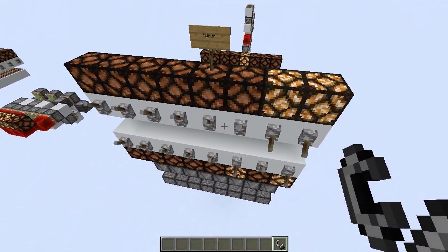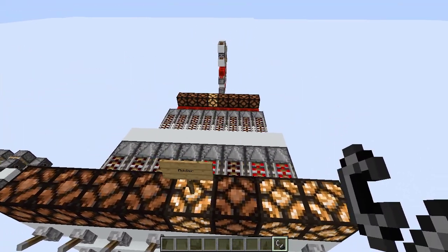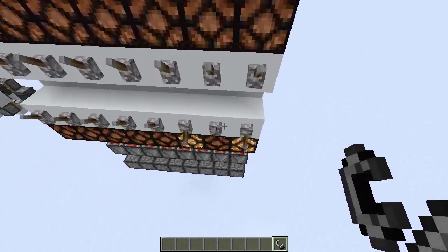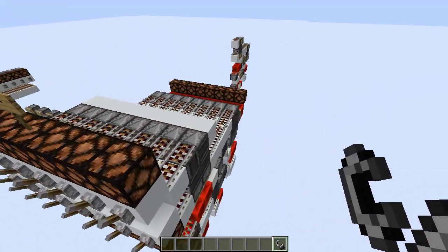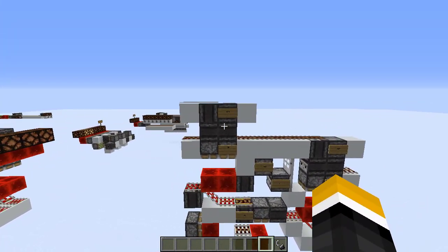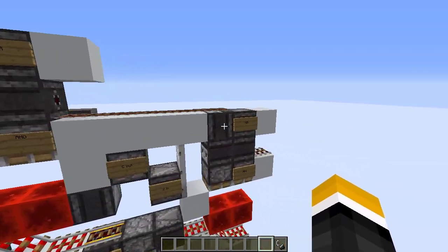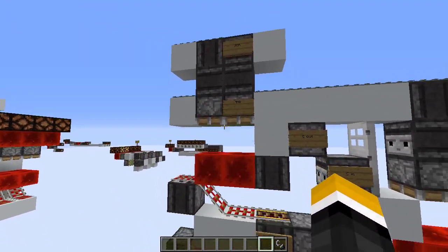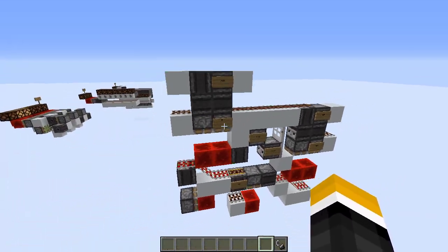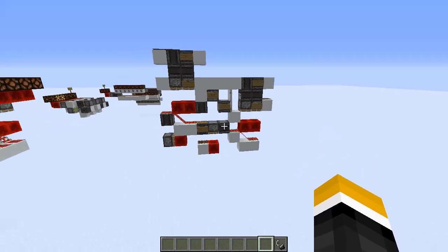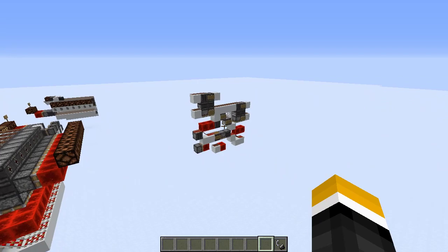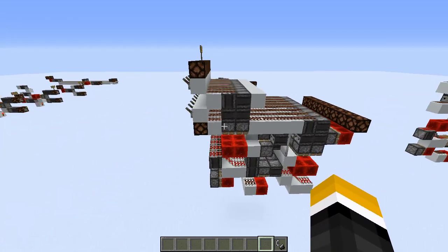So the adder works. It's a simple ripple carry adder. You can turn it off with this. The way it works is just like any ripple carry adder. It has 2 XORs, 2 AND gates. Those link together using an OR gate to create the carry, and has obviously a carry in. I don't want to go into too much detail over how this logic works, but it's essentially just these logic gates over here put together inside a simple contraption.